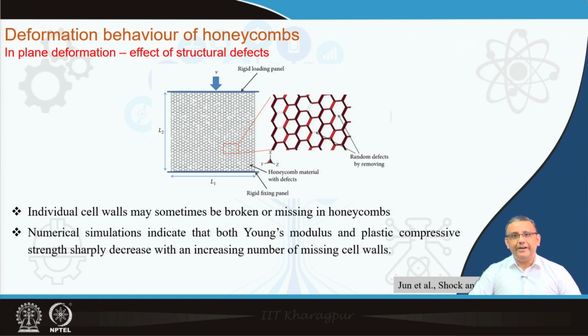We also learned that when such a honeycomb is compressed by external loading, the deformation propagates in the form of deformation bands. These bands initiate at a weak location, and the cells very close to the initial defect in that band deform first. Then, as we deform the honeycomb more and more with more external compression, more cells join the band and the band propagates.